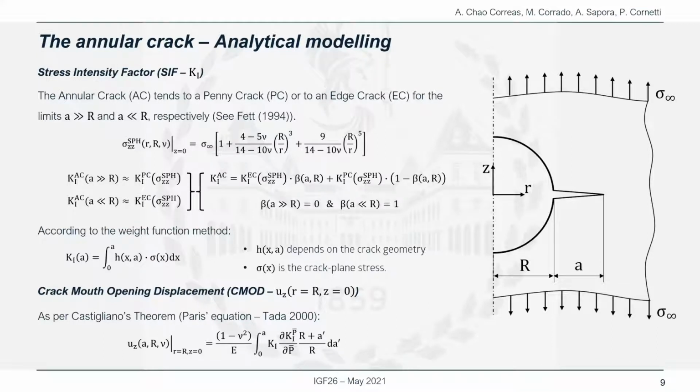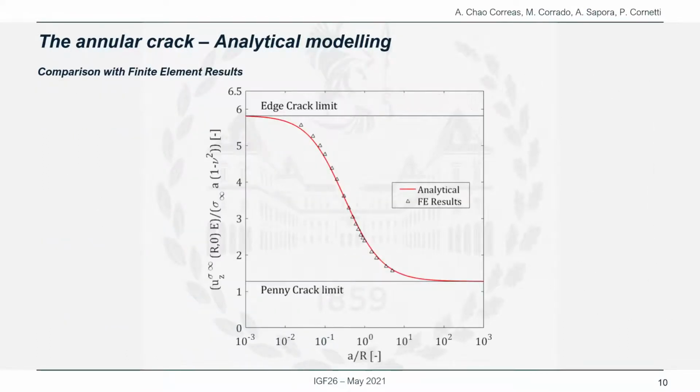This relation is also rather interesting for the comparison of the analytical and the semi-analytical stress intensity factor functions with finite element simulations. Through this semi-analytical procedure that we have just presented, it is seen that upon a correct choice of the beta function, very good agreement might be obtained in comparison with finite element results.